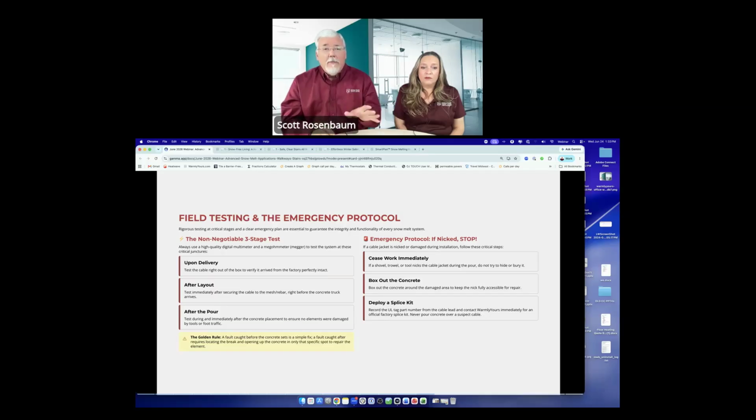Two big differences. The multimeter is used for testing ohms. The megohm meter is used for testing the insulation between the two heating wires and the ground that are inside the wire. We're testing the insulation value between the one core wire and the other core wire to ground by sending 500 volts down that line. So a megohm meter is actually testing the wire under stress to see if it's going to be good. A multimeter does not do that. Many electricians have megohm meters, and if they don't, they're readily available. You can find them everywhere, but you're going to need both to do this job.